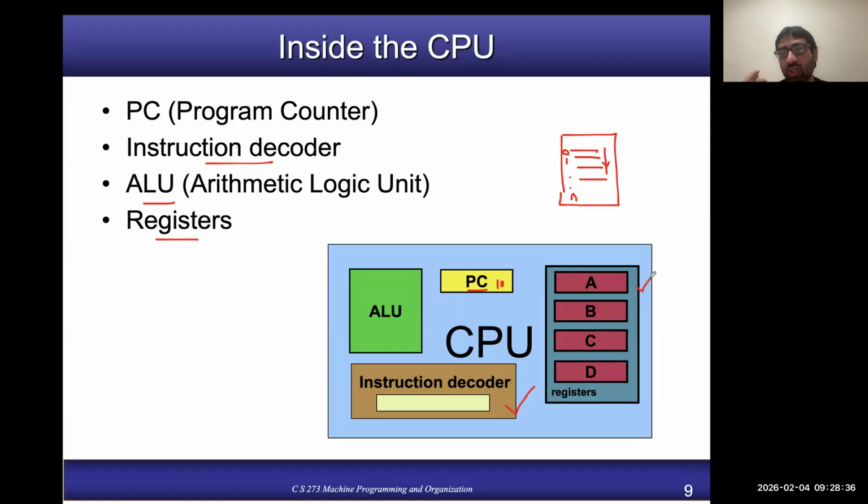Here we have kept it very simple by naming the registers A, B, C, and D. If our decoder found that the data is in register A and register C, then the data will be fed from A and C into ALU, and ALU will do the add operation. And if the instruction also tells to write the data back in register D, it will be written back into register D. Okay.